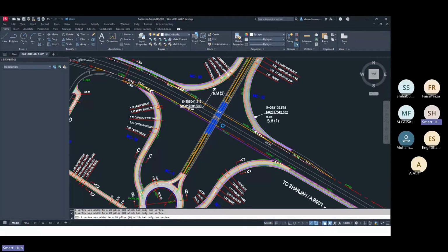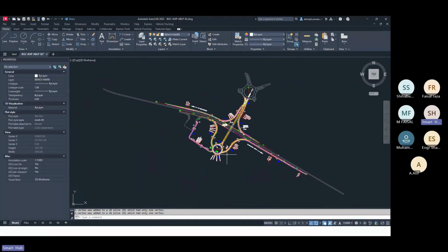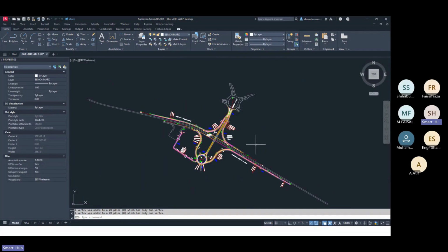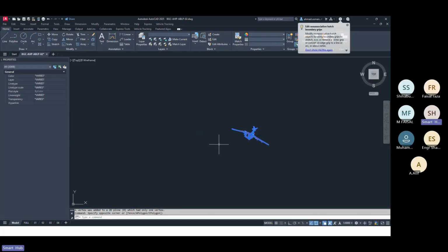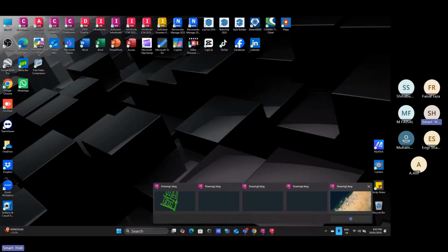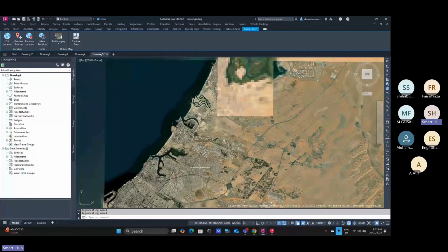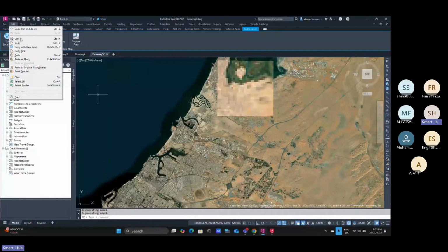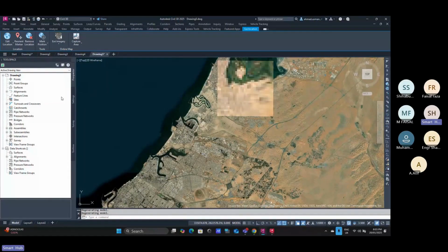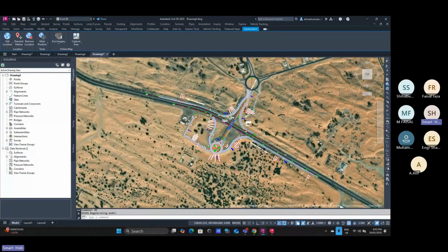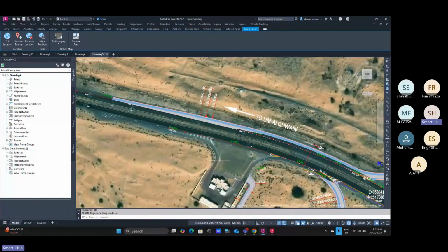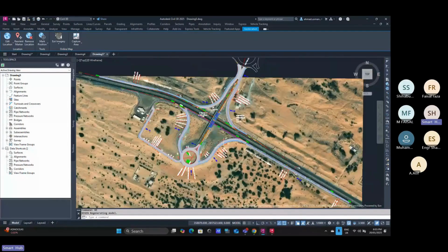All right. Now, all of them have come down to a complete 0 level and they've been thoroughly flattened. This process has confirmed that all the vertices, however numerous they might have been initially, have now all been converted to a precise 0 level, just as all the associated objects have also been transformed. Once you have completed this crucial step, carefully select all these transformed objects, then use the familiar Ctrl+C shortcut for the copy command, and subsequently return to Civil 3D, because it is essential that you continue your work within the Civil 3D environment for the next stages of this project.